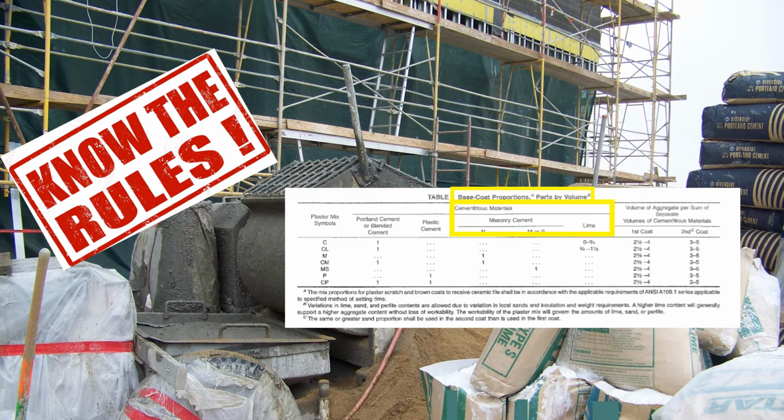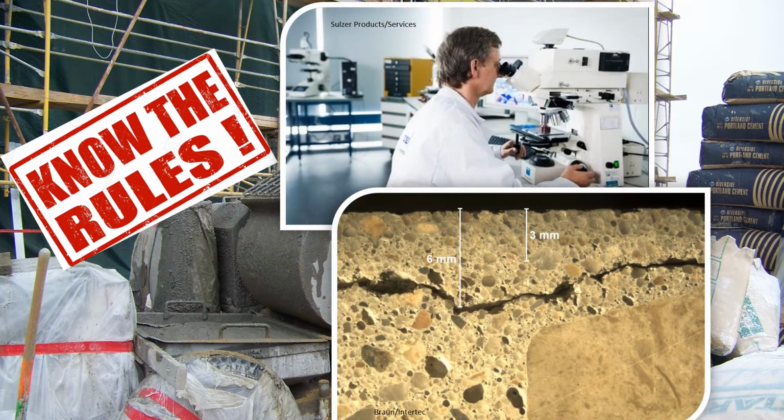That lime is classified as a cementitious material. This means if you make your own mix, you have to be very careful as to volume of lime added to the cement. Adding too much lime, not enough cement, or sand that is non-code compliant, you are in non-conformance to ASTM mix. If you think no one will know if your mix is too rich, has unwashed sand, or non-angular sand, you need to know about the Petrographic Analysis.